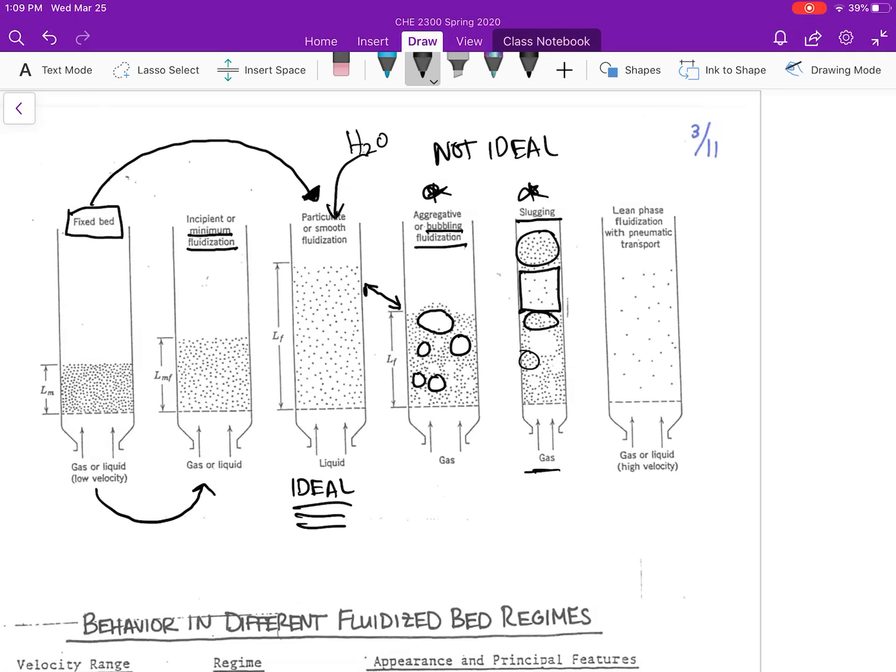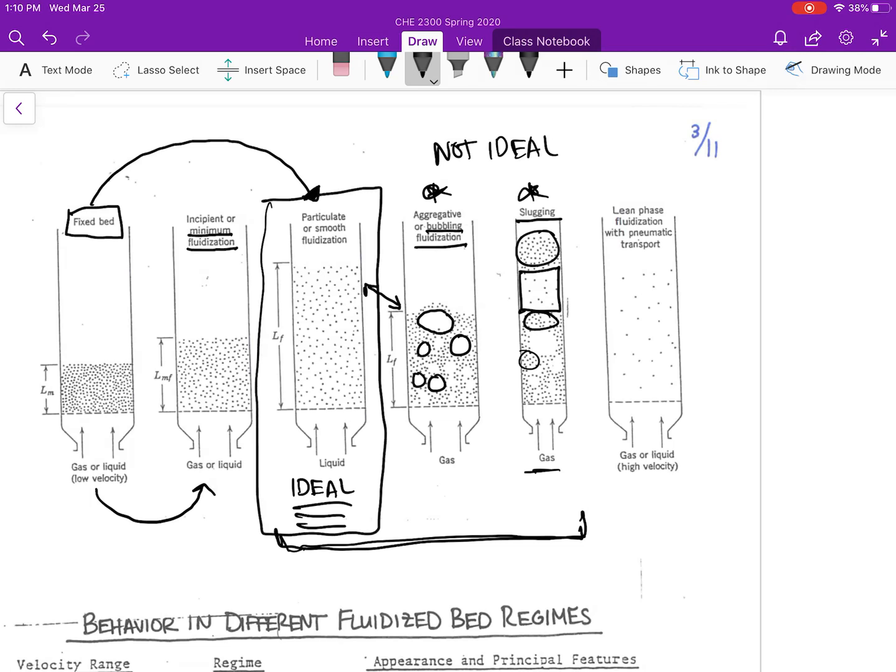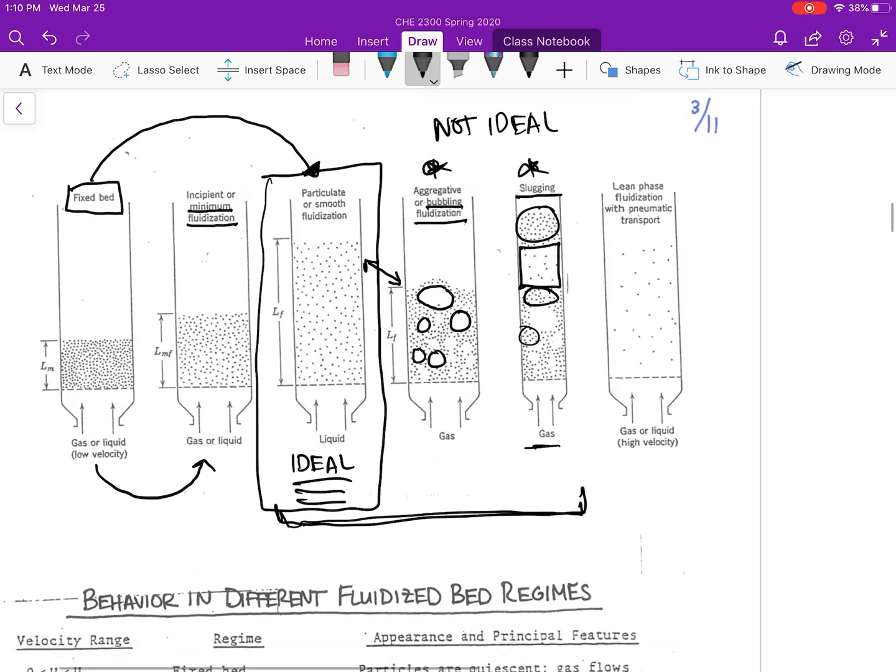If I have H2O coming from the top, air plus SO2 coming from the bottom, having those particles, I don't want to use that example, because in that case you're actually using a packed bed, not a fluidized bed. So I'm not going to use that example. I think I've made my point here that if I compare these three fluidized beds, my fluidized bed here on the left presents the most ideal scenario because I have even distribution of my fluid throughout my fluidized bed.